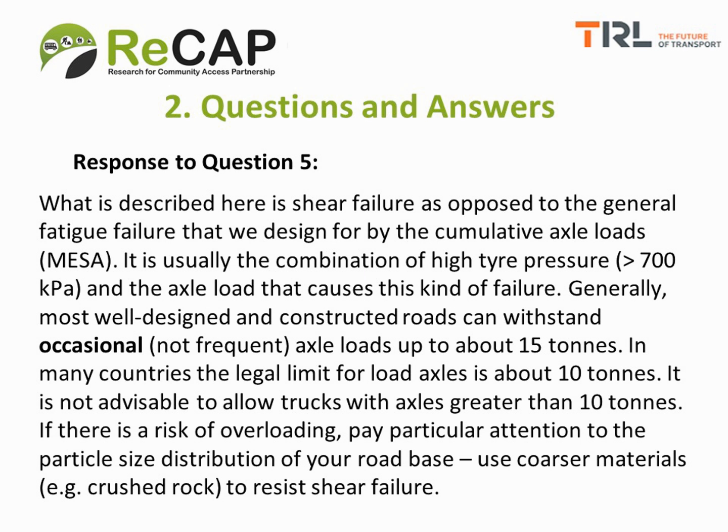The question was, what's the difference between the designs for low volume roads and high volume roads? What is said here in this question is, can we allow heavier vehicles than the 10 tons? And as you've said, occasionally the low volume roads will be able to withstand a few heavier axle loads.